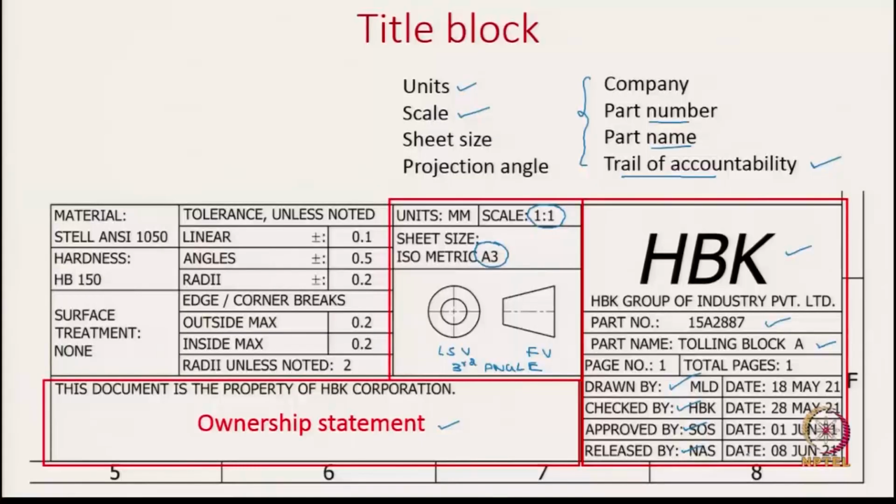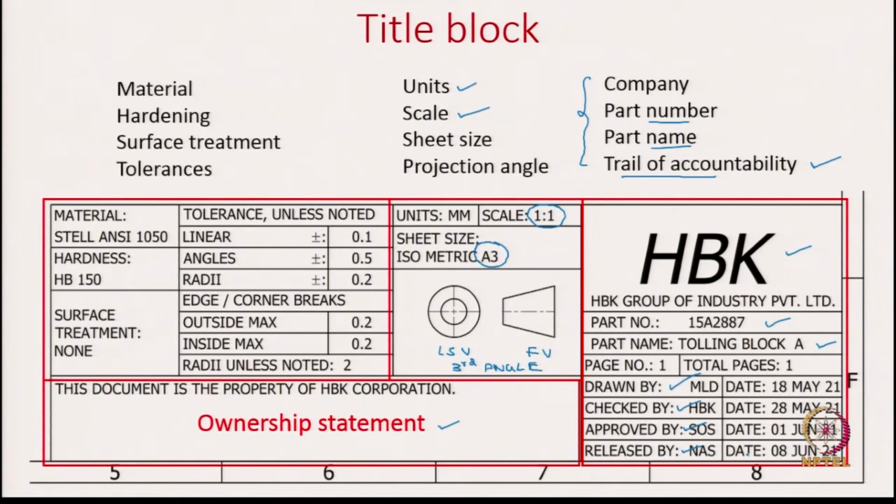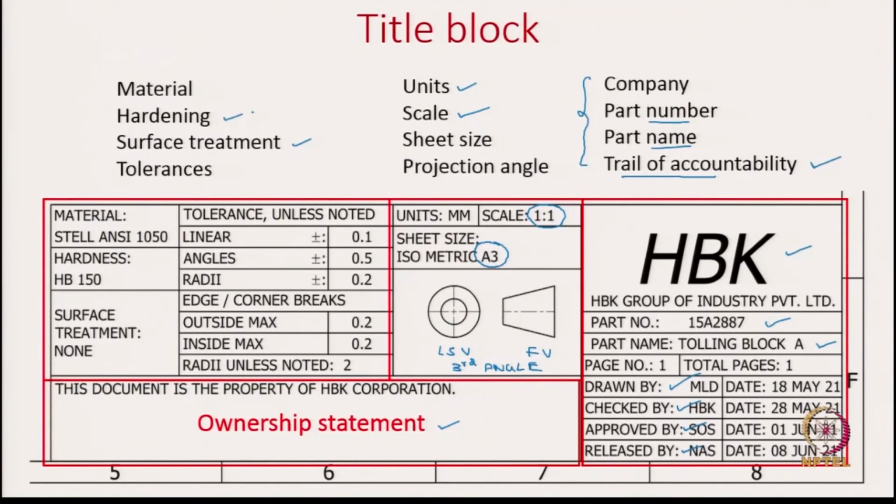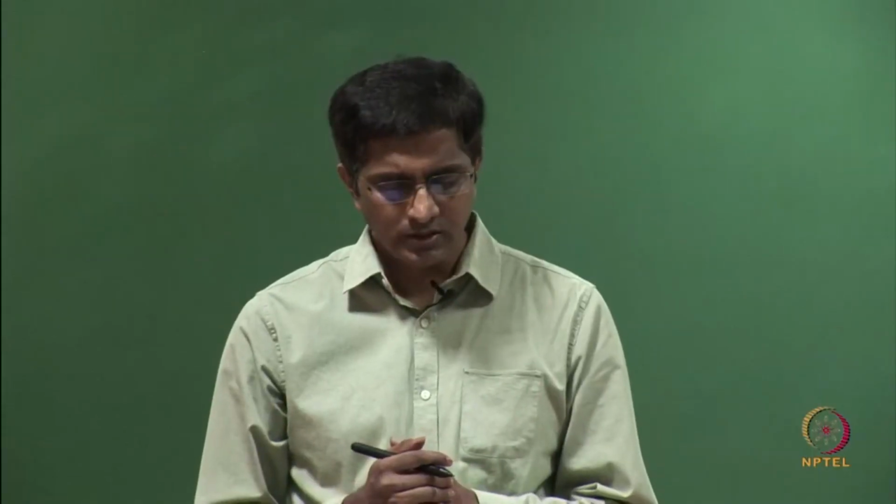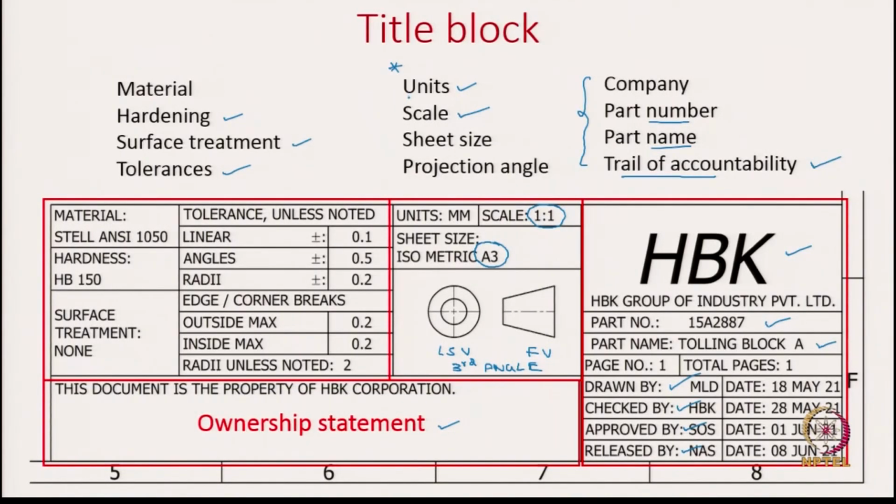Okay. And the last information we have in this title block is the details of the material. You need these details when someone is fabricating the object. They need to know what material they should use to prepare it and any specific treatments they need to do, something like surface treatment, the hardness of the material, and the tolerances. This being an introductory course, we will not go into too much detail on all this, but I think this is more important, where we specify the units we use, scale, sheet size and projection angle.